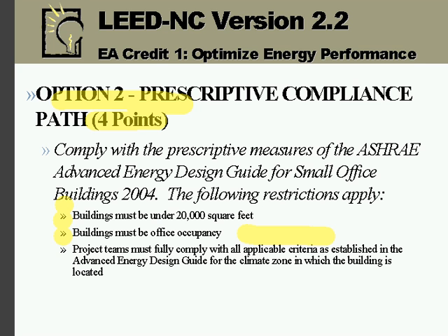Basically, you need to go through to the page that I showed you, which is the prescriptive requirements, create a spreadsheet and say, yes, I needed this much insulation. Okay, this is how much insulation I put into the space. Here's my watts per square foot. I'm at 0.85. Good. All you have to do is do the spreadsheet that shows you prescriptively met the requirements.